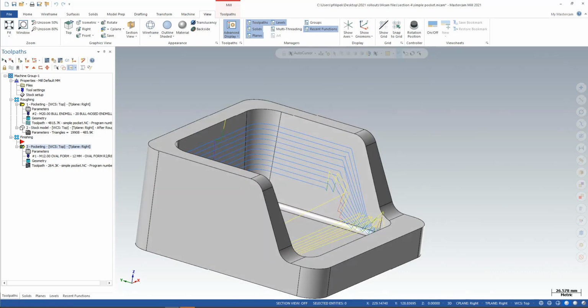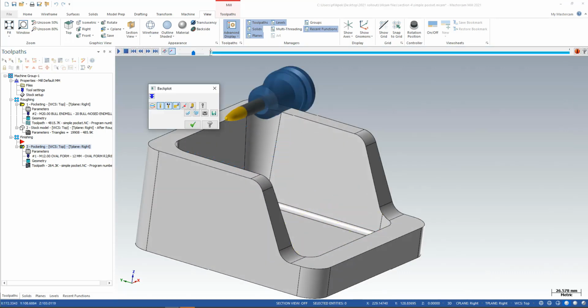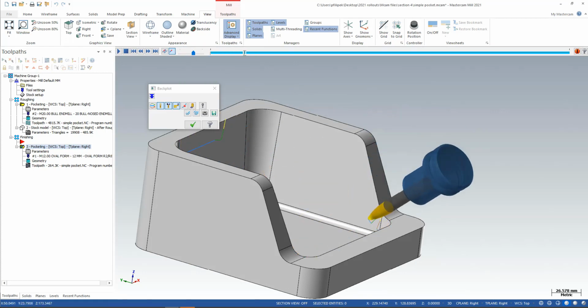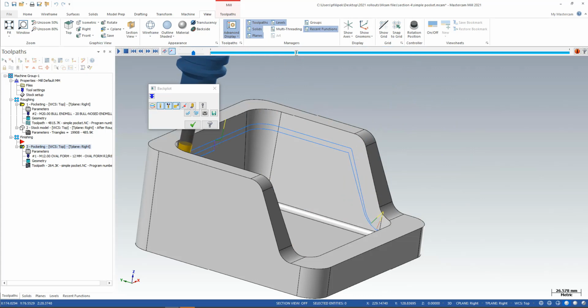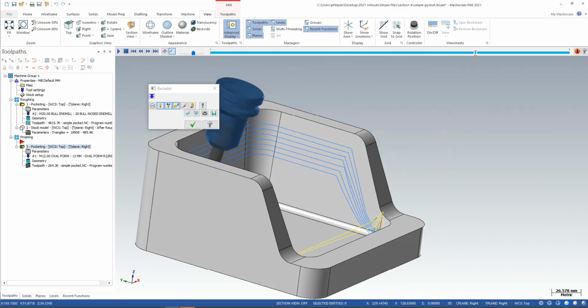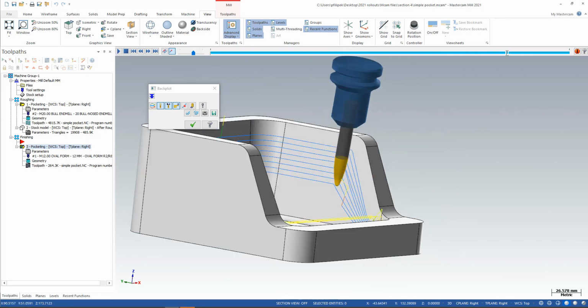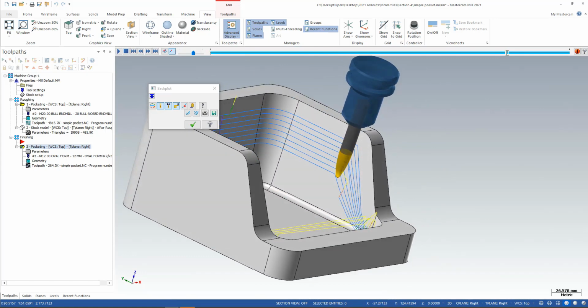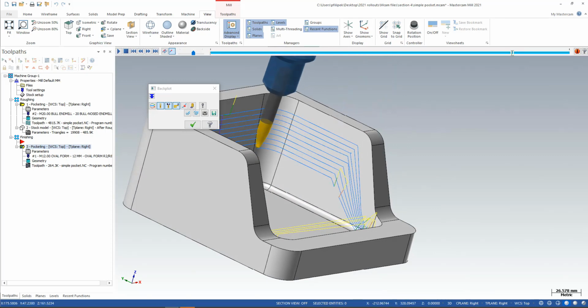And we got a cut along there, just not a great cut. If I look at this, it's doing exactly what a morph should do, right? It's morphing the top ceiling to the bottom floor, and it's cutting. And you'll see that it starts to lose its mind a little bit right there. What happened was it cannot maintain a cut between 40 and 60. So it had to trim the tool path back and relink it, and that's what you're seeing there.